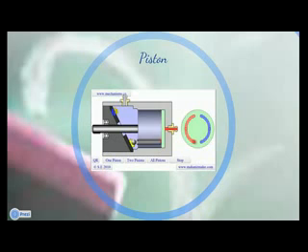The horizontal distance between the top left and bottom right are fixed, and thus the name of the pump, fixed displacement pump, is derived from this fact. While the round end of the piston rests on the yellow shoe, which is sliding on the black swash plate, the other end moves closer to the green port plate during half of the rotation, and moves away from the green port plate during the other half of the rotation.